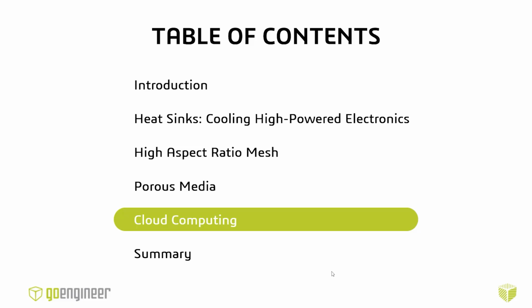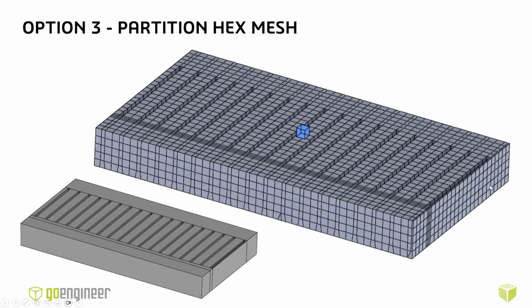But getting into 3D experience and other types of structured meshing, other types of solving capabilities available to me, cloud computing. I'm going to start with partition hex mesh and this idea of the structured meshes. The 3D experience platform doesn't require that I use this meshing method. I could use what methods I was doing formally in the presentation. But this is just an intriguing option that I can take advantage of here.